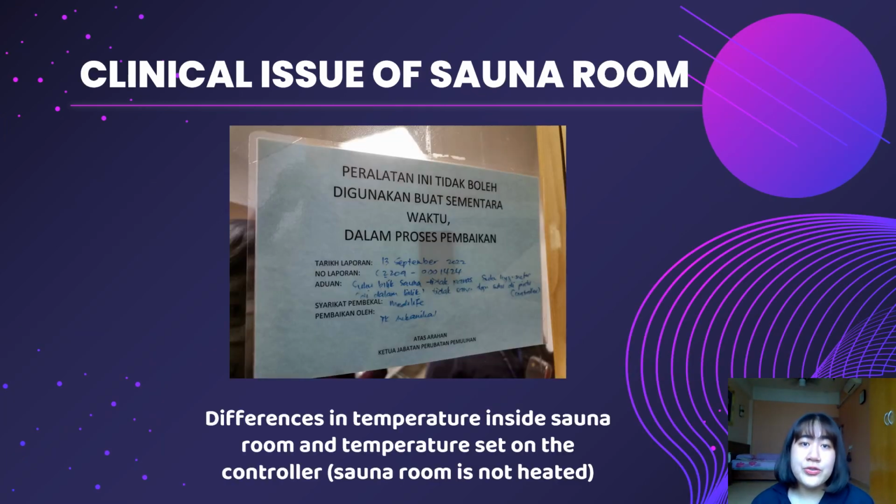For the clinical issue of the sauna room that we discovered through our visit to the physiotherapy division, there is a difference between the temperature inside the sauna room and the temperature set on the controller, so the sauna room is not heated. This clinical issue causes the sauna room to require maintenance and it can't be used by patients for therapy. This clinical issue may happen due to inappropriate placement of the electric heater in the sauna room or malfunctions in the heater or controller.